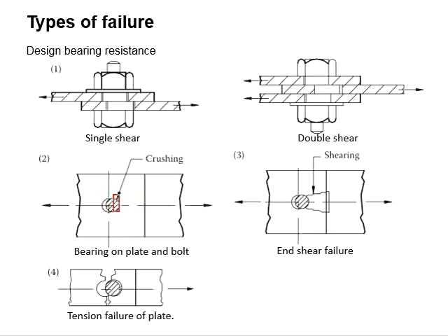The contact between the steel plate and the bolt will be the bearing area. Based on the principle of static equilibrium, the total resistance by the bearing load will be equivalent to the total tensile force acting on the plate. And it is assumed that the bearing area remains in the plane form.